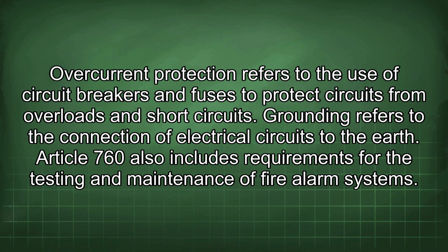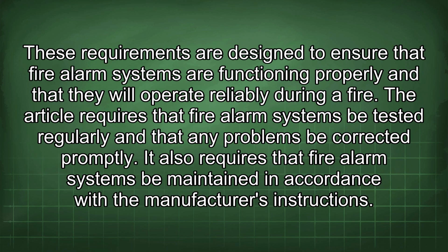Article 760 also includes requirements for the testing and maintenance of fire alarm systems. These requirements are designed to ensure that fire alarm systems are functioning properly and that they will operate reliably during a fire. The article requires that fire alarm systems be tested regularly and that any problems be corrected promptly. It also requires that fire alarm systems be maintained in accordance with the manufacturer's instructions.